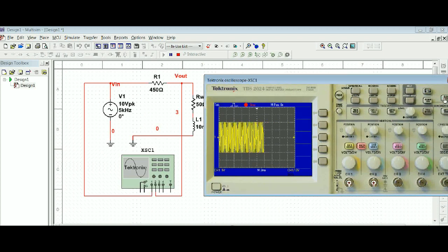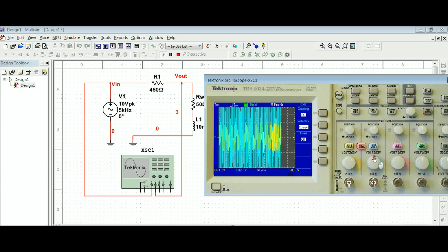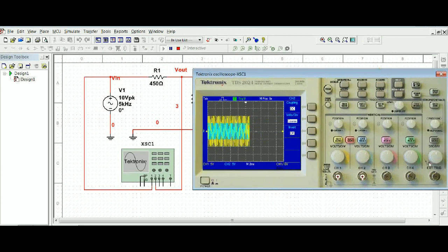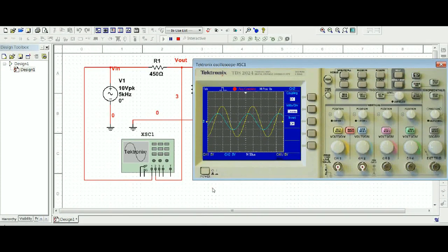So getting it running again, I'm now going to turn on channel 2. It's also too large, so I'm going to change its sensitivity, and maybe I'll make that 5 volts also, 5 volts per centimeter. Now I can't see this all too well, so what I need to do is come over to the time base and spread things out a little bit. Yeah, that's pretty good. Let me stop it. And I'm only getting half the signal, so I'll click on single. It'll give me a complete shot here. Now what you gotta not do is click on reset, because that'll reset every single thing.